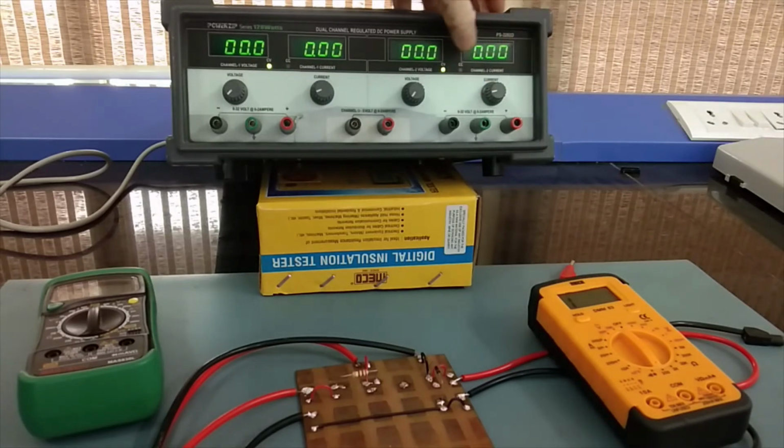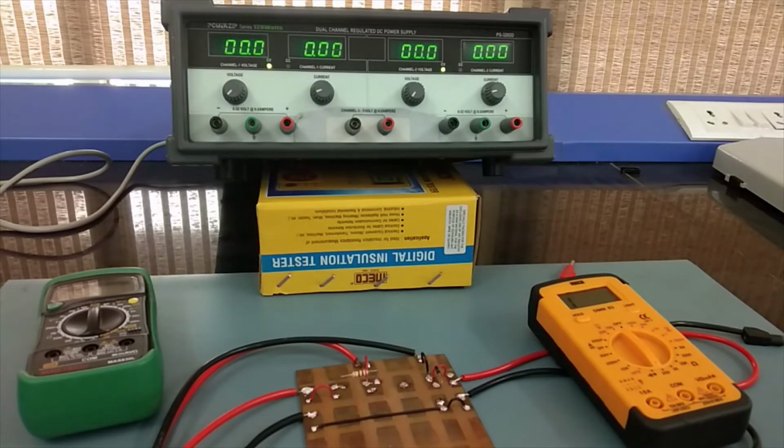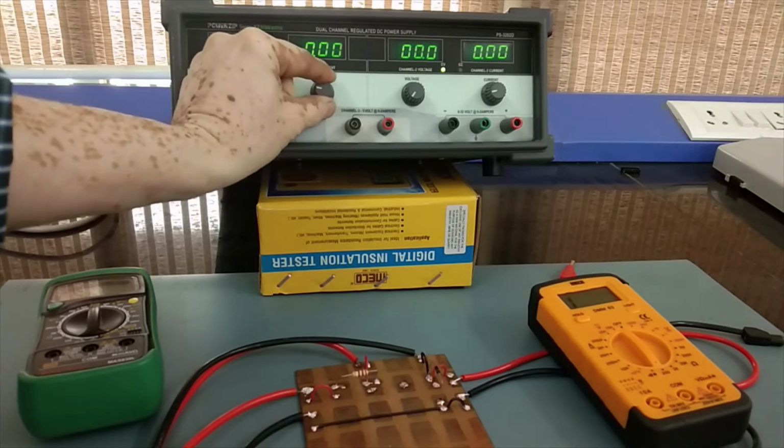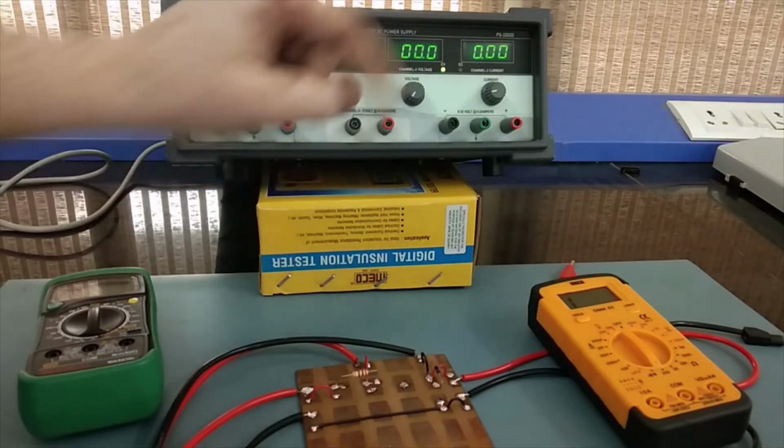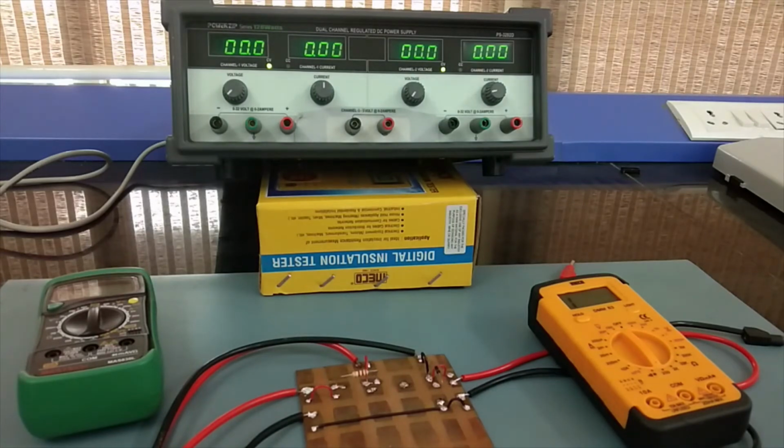If you have to increase it, once you increase, this red signal is no more. The diode is off right now. Here you remember that if you come across such indication in your circuit, be very alert. It may so happen that there is a short circuit in the circuit that you have prepared. Because under such circumstances, if there is a short in the circuit, then the current demand of the circuit increases drastically and the power supply asks for more current. Many times it happens that we do not understand the necessity and immediately we increase the current knob. It may so happen in such a case that your entire circuit will be burnt and you may harm yourself also. So therefore, whenever this is red, be very careful to what action you are actually taking.